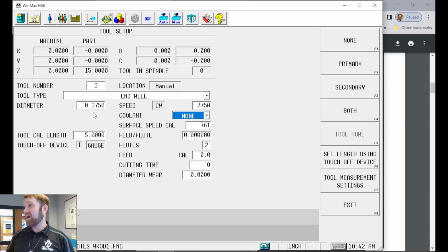As a matter of fact, our tooling actually has a variable based on how you're using the tool. We program everything based on slot milling, and then we just run it at that. But it also has profile milling, which is a higher cut speed, and then it's got high feed milling, or high speed milling. Sorry, I don't want to get the statement wrong there. High speed milling, which means a really light step over, but the full flute. But you can feed it super fast. Okay, you're just basically running it around there, and it calculates out to about 300 inches a minute for a 1/2 inch end mill, compared to like 90 is what we're going to get here in a second.